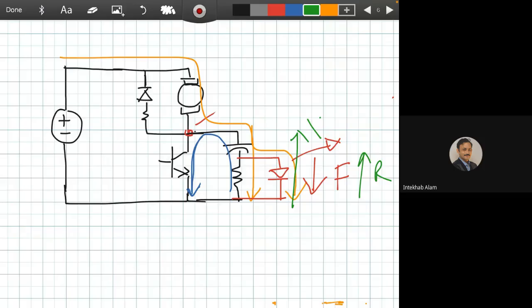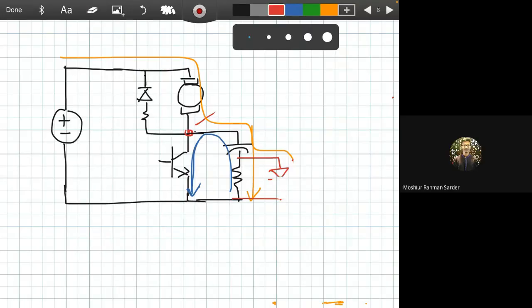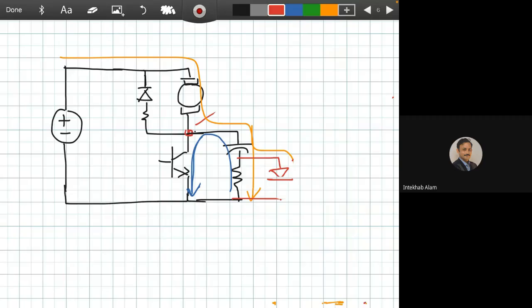Okay, so now we have another story of the diode. Now we need to protect this diode, because whenever the capacitor charges through this diode, it will become a short path, so the diode may burn. So we need to protect this diode again. How? We need to add a resistance. We need to add a small value of resistance here. If we add a resistance here, you will find it as an active diode.